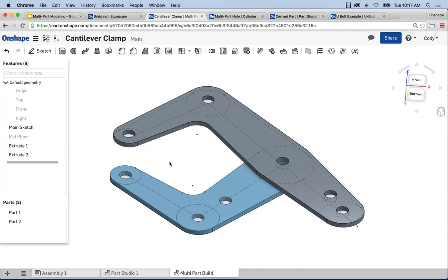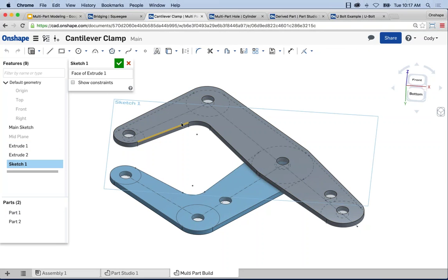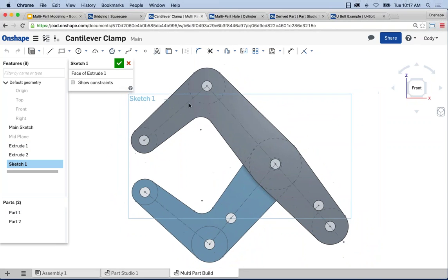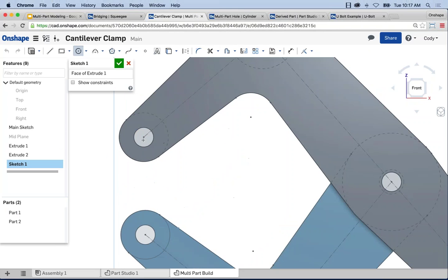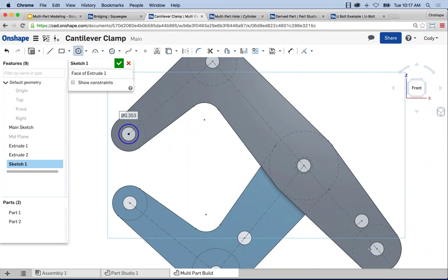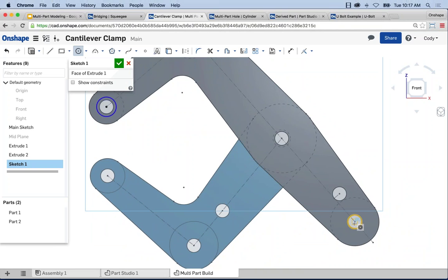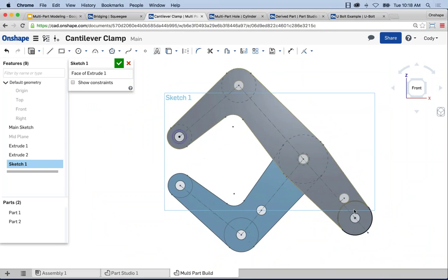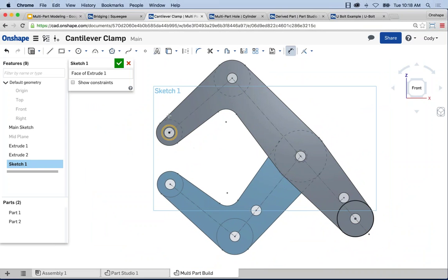I want to build a series of pins. So what I'd like to do is just create 2 sketches. Okay? And really what I'd like to do is just attach these 2 sketches to my first sketch. Right? Again, I really want that first sketch to drive everything. Okay? So I've created 2 circles. I'm constraining them to the first sketch. Right? So they are attached.